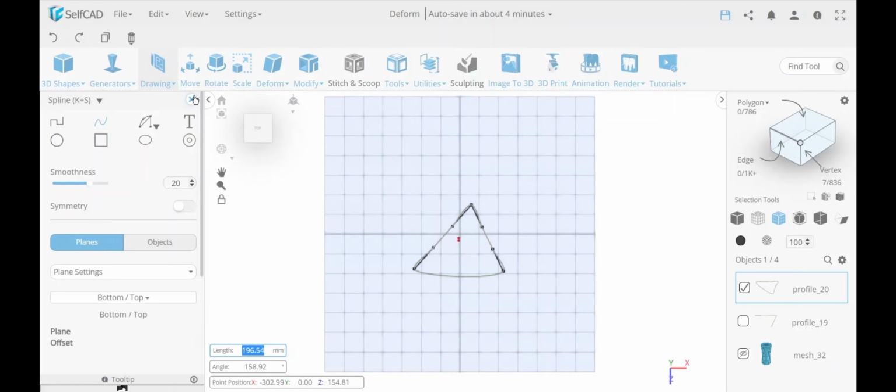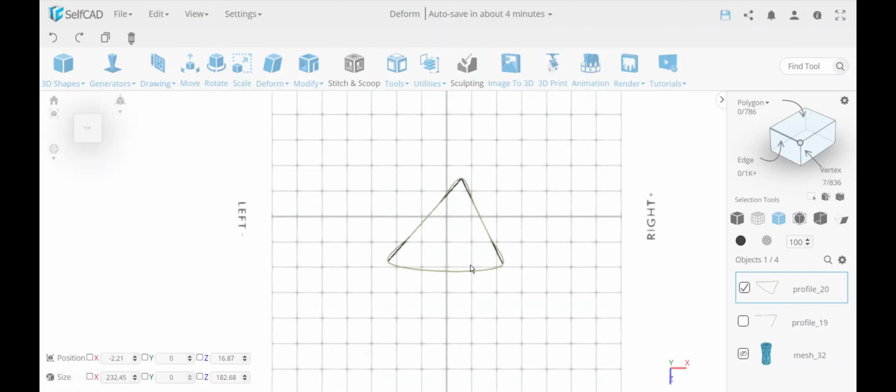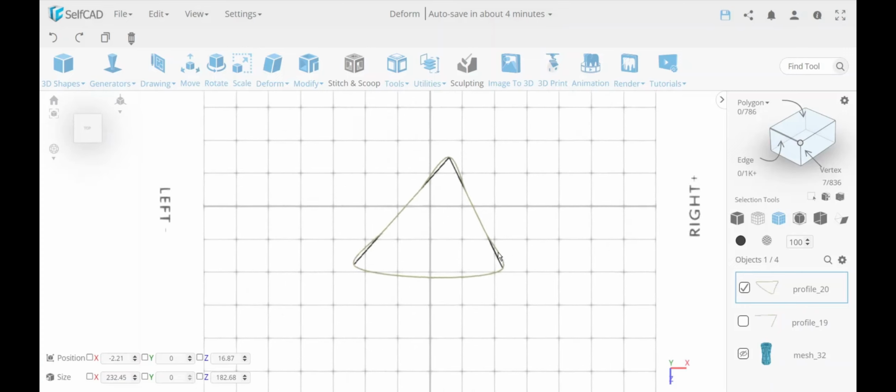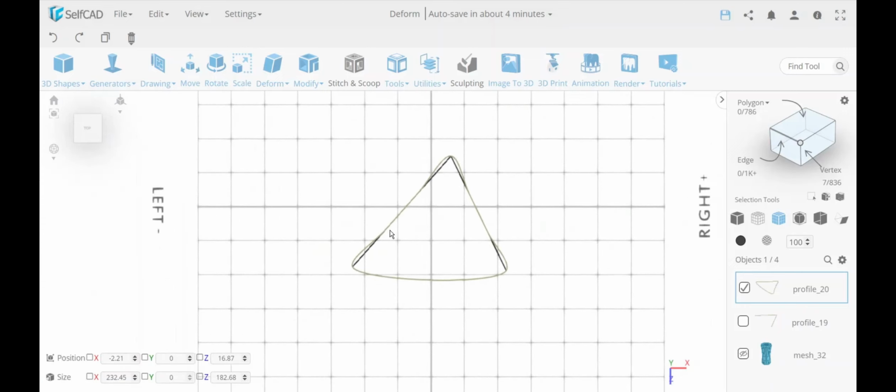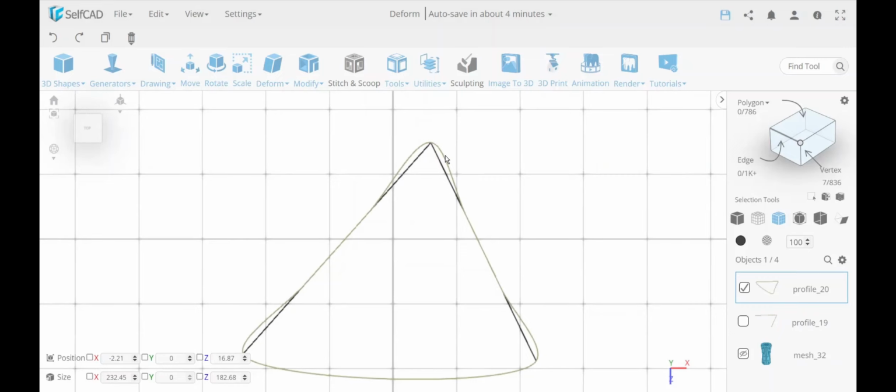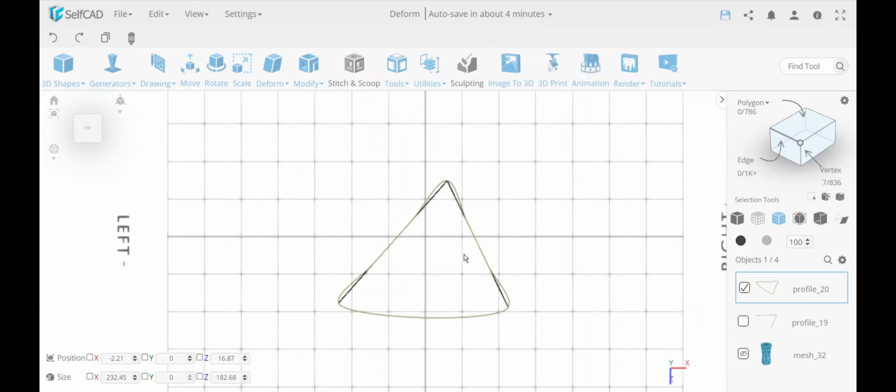So look what happened over here. Over here, because I had no points, I made a big leap between here to here. It actually rounded over here the entire thing, including the outside over here. Over here that I had points, it didn't touch it, nothing got rounded. It kept it, and over here, there were basically no points. Here were less points over here. It rounded this entire thing. So it kept the shape a lot more intact, hugging the original shape, because it had more